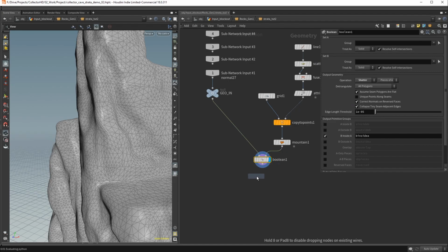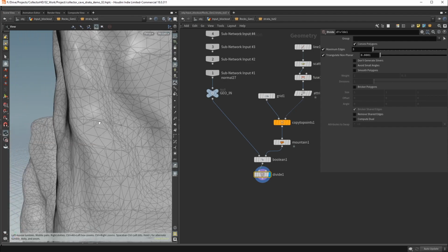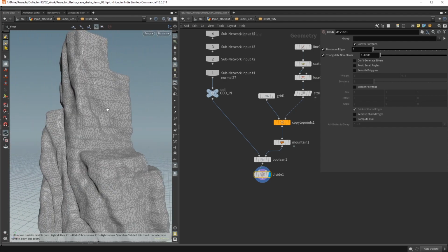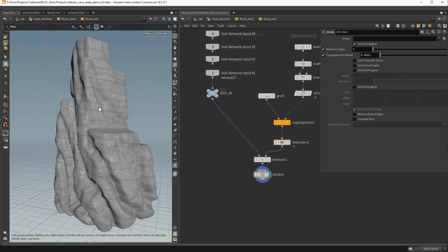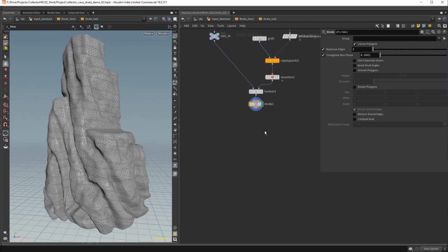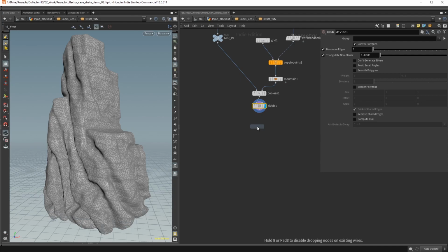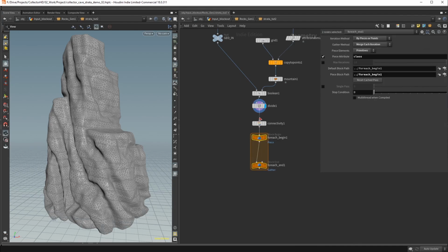You can use a divide node to just triangulate the polygons around cuts. This makes things even easier to see. Okay, now we have our cuts, and we can use the for each connected piece loop to work on each layer separately.